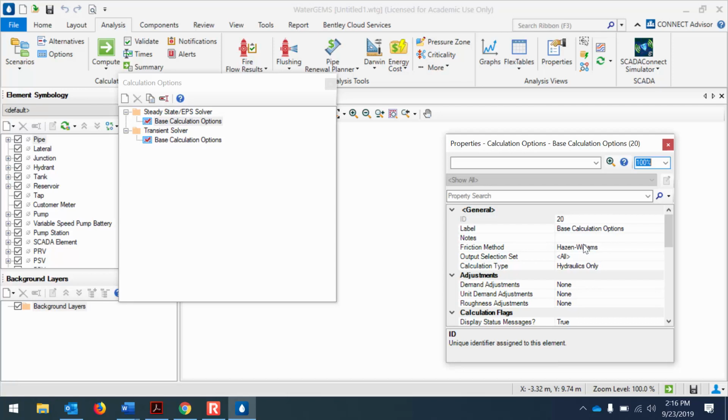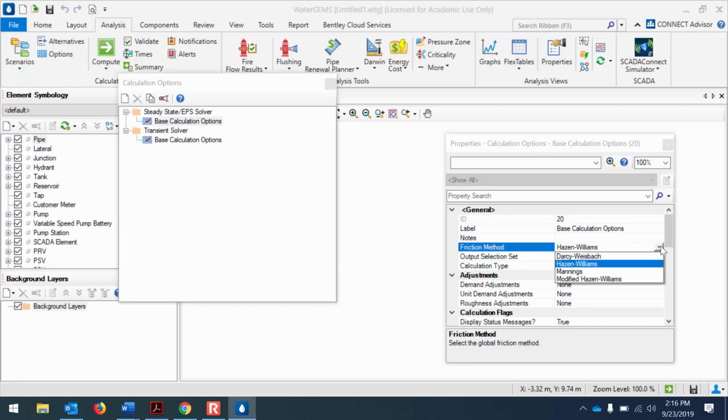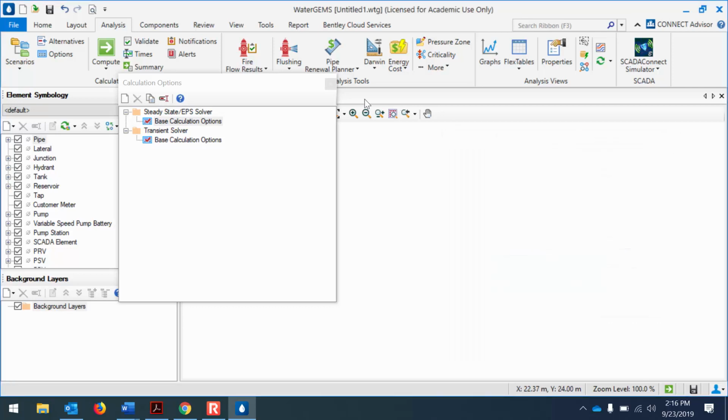So Hazen-Williams is great if you're doing hand calculations, but frankly I don't know why it's even an option in this program, because I don't care if it takes the computer another half second longer to do the calculation. So instead of Hazen-Williams, in the drop-down box, what you should select is the Darcy-Weisbach. The Darcy-Weisbach equation is applicable over a much wider range of hydraulic and physical pipe diameter conditions. So it's more often going to be applicable, but just on top of that, it's always more accurate. So select the Darcy-Weisbach in the solver.